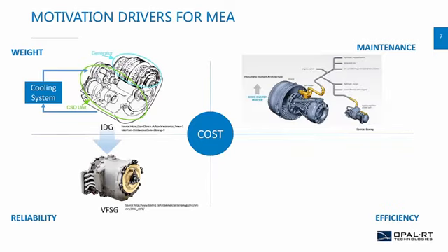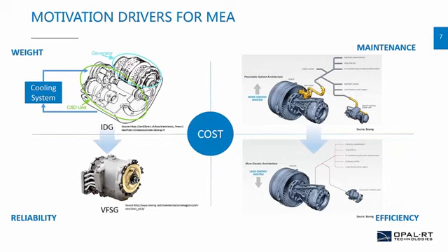As well, for the traditional setup on an aircraft, the bleeds of the engines and the APU and the start sequence are used to feed conventional loads such as hydraulic components and pneumatic components as well. Going to a more electric strategy will eliminate the use of those bleeds, therefore reducing the losses on the aircraft engine and also reducing the maintenance of such a bulky system by replacing it with an electric system.